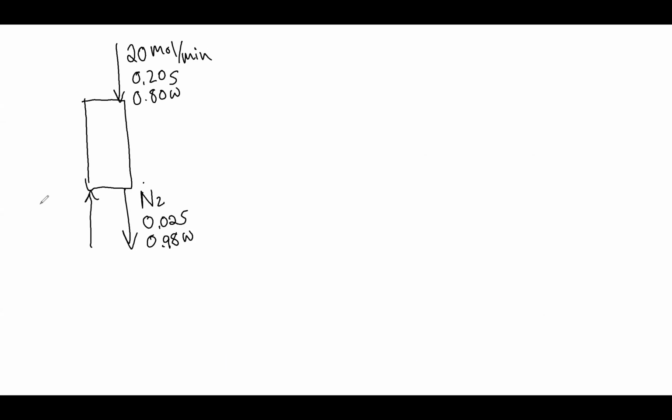On the other side, we had pure air coming in at 48 moles per minute, 0% S and 100% air. And here we did not know what the outlet flow rate is. We'll call that N3, but I'll use the number that we found from last time. 0.078 was our mole fraction of S, which means that the balance, the other 92.2%, must have been the air.